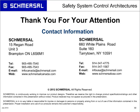The other scenario is somebody opens up door number 2 first, even though a fault has occurred on door number 1. Because you opened up door number 2 first, then open up door number 1, the safety relay is still satisfied. That's why the most you can achieve is control category 3, because of certain faults that can occur in the system. But it's also a reason why there's a difference between series wiring category 3, category 4, and some of the failures that can go undetected, where category 4 doesn't allow that to happen, or shouldn't allow that to happen. You need to detect any failure and prevent the machine from running until you fix it.